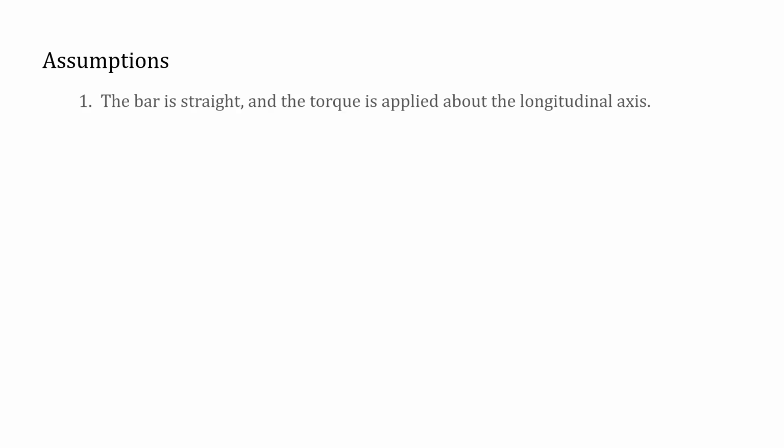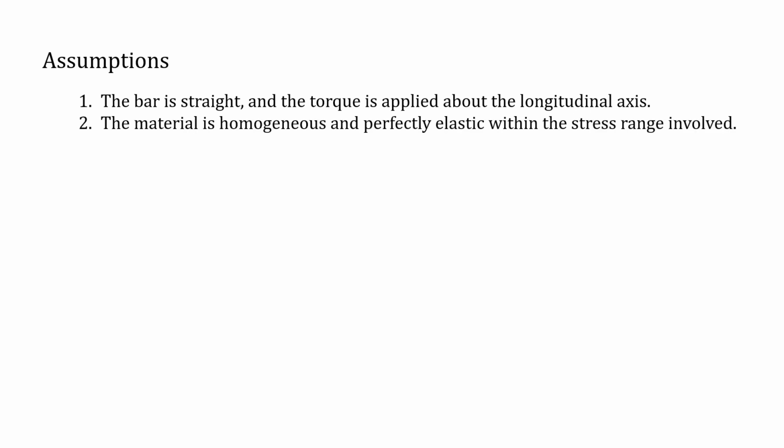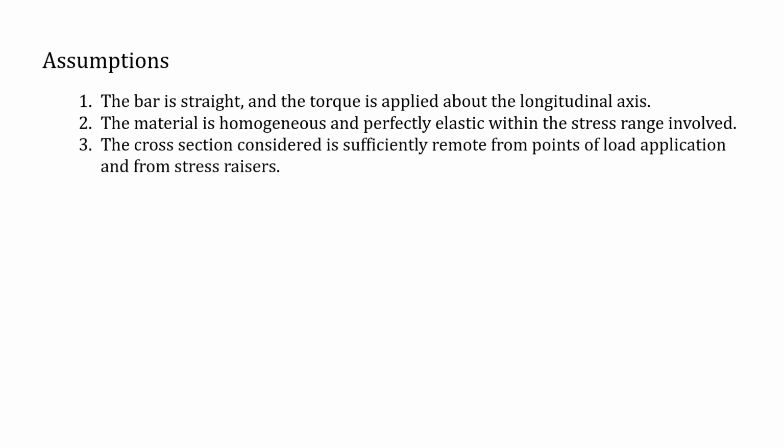So we have 3 assumptions to make for this problem. The first being that our torsion bar is straight and that the torque is applied about the longitudinal axis. The material is homogeneous and perfectly elastic within the stress range involved, so we don't have any plastic deformation. The cross-section is considered sufficiently remote from points of load application and from stress raisers. So those were all of our assumptions.